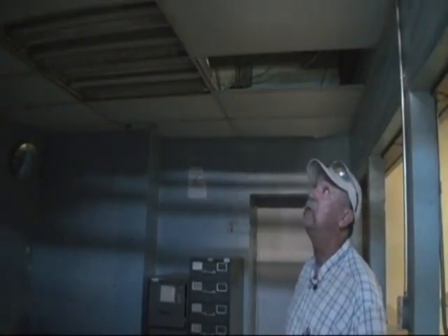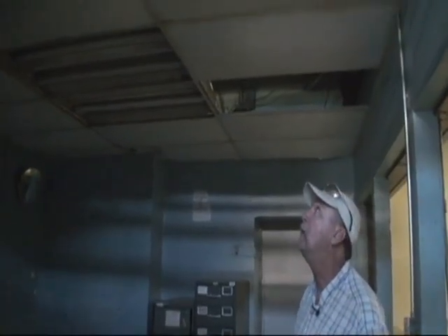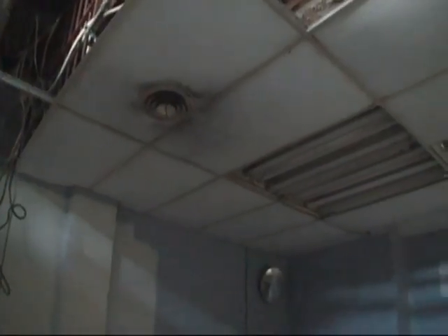Ceiling tiles, drop ceiling tiles are another asbestos containing material you can find. There's a lot of different styles and shapes and configurations of tiles. These would be considered a friable asbestos containing material. It's not often that you will find asbestos in ceiling tiles. Typically when you do encounter that, it's in school buildings, big box buildings. You need to be careful when you remove those kind of materials.